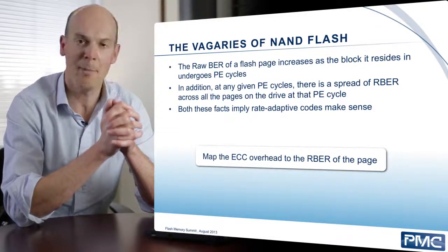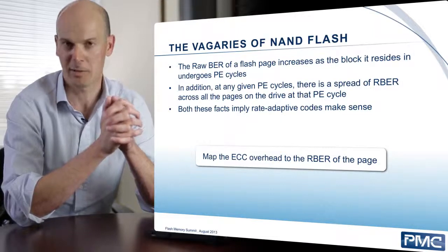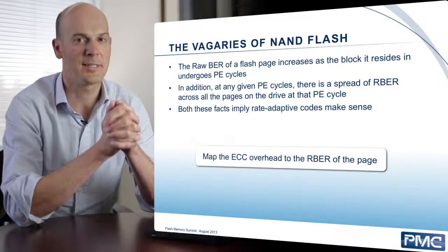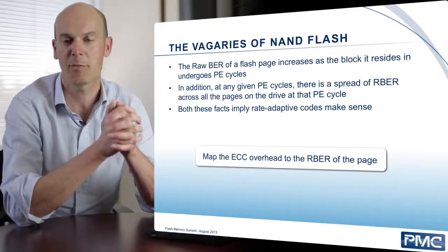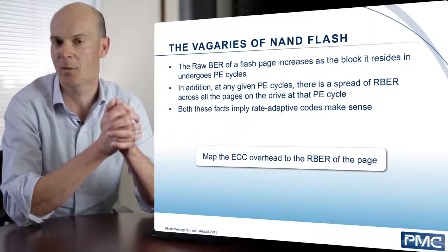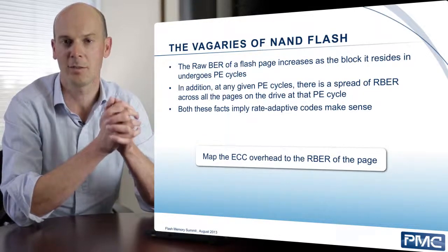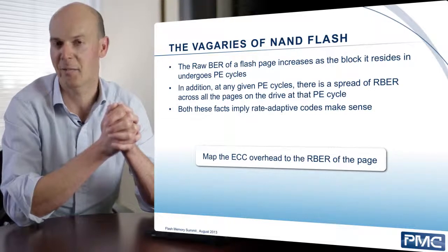One of the things that happens with NAND Flash is that it gets degraded as we use it. The usage of a flash is measured in terms of program erase cycles. Every time you write new data to the flash, you have to erase and reprogram it. And every time you do that, a slightly destructive effect inside the device causes it to wear out. Over a period of time, the ability of the drive to store your data reliably is diminished.